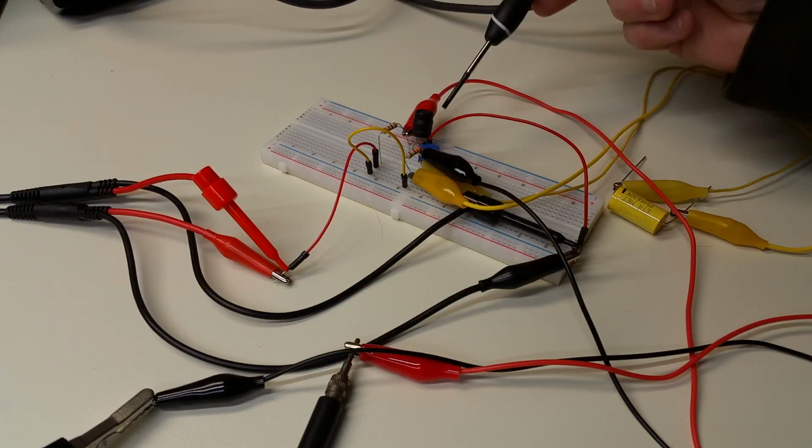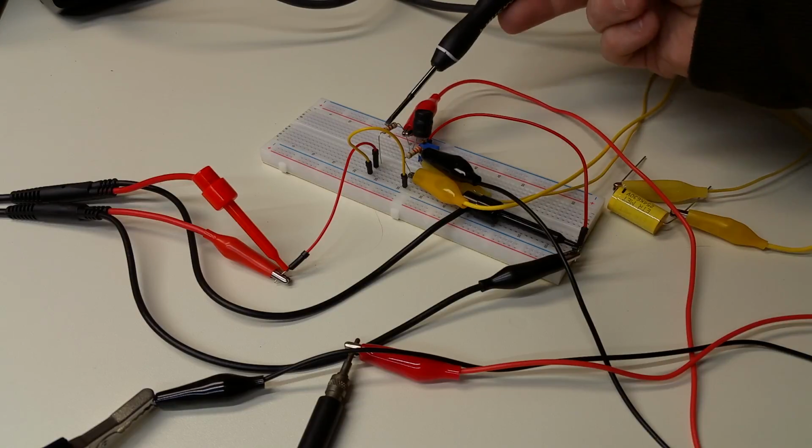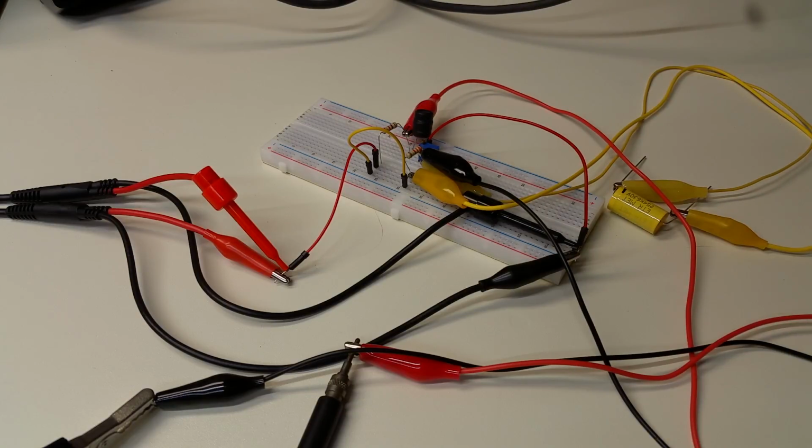So I've wired up a bridge circuit here, and I've picked some values of my two fixed resistors, and I've picked those to be 220 ohms and 3 kiloohms, because those were what were in arm's reach. I have a little potentiometer here, which is a 10K potentiometer that I'm going to adjust. And I have this rather large, physically large capacitor, which is 1/4 of a microfarad in value. And I've set up a function generator to produce a sine wave at 10 kilohertz.